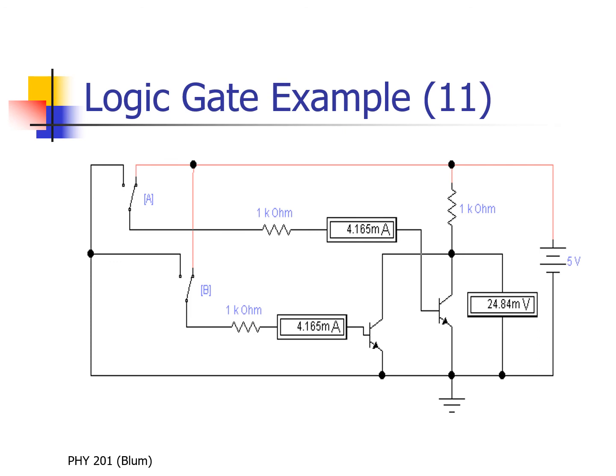transistors acting as resistors with low resistance, and they're in parallel, so that makes the effective resistance lower yet. And so the 5 volts goes through the 1 kilo ohm resistor, and then these two low resistance acting transistors in parallel, and so most of the voltage is dropped across the 1 kilo ohm, only a little bit of voltage is dropped across the two transistors that are both on and in parallel.